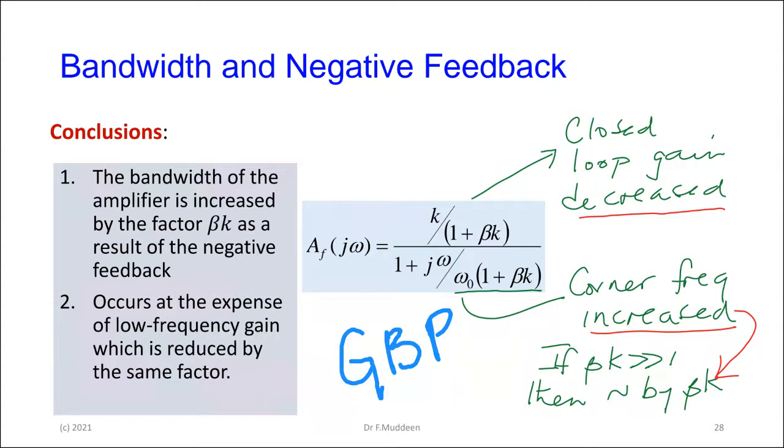That is why the amplifiers and op-amp makers, for instance, give you this thing called a gain bandwidth product, because what happens is that as you tend to increase the gain, the bandwidth drops, or if you increase the bandwidth, the gain drops. So you have to work within those parameters to see exactly what you want. You can get high gain but very small bandwidth, or very wide bandwidth but at lower gain, right?